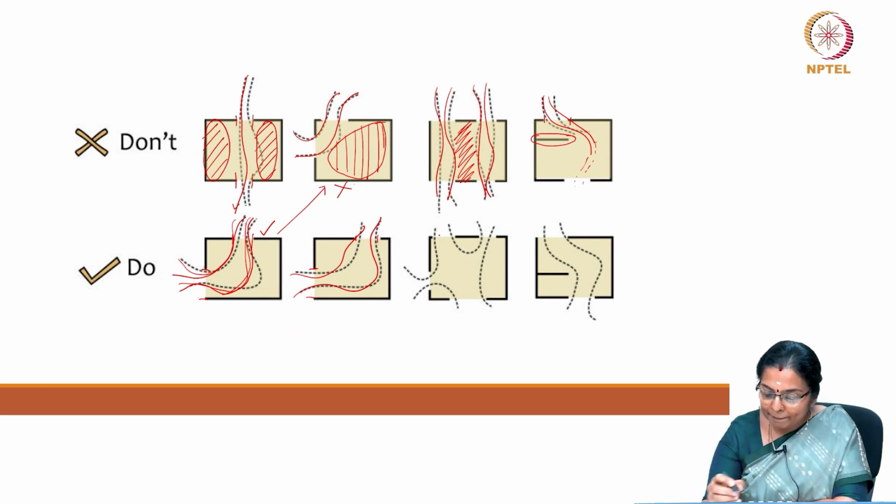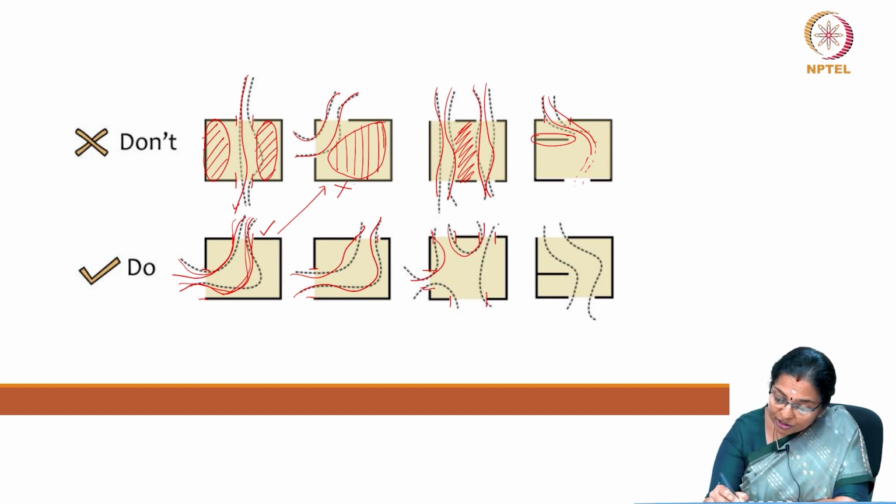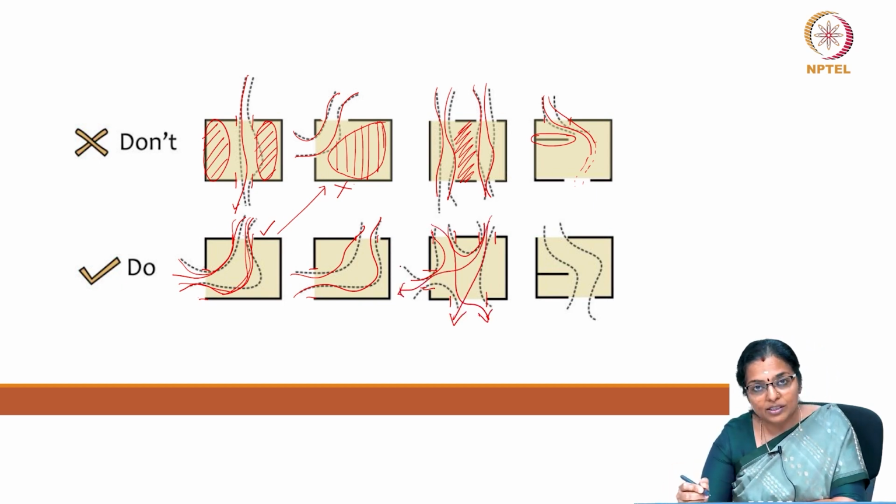This is another very good scenario where you have breeze flowing in all across the room, covering maximum area. Having openings along 3 walls again ensures very good ventilation, because breeze can flow from one place to another and ventilate the entire room.